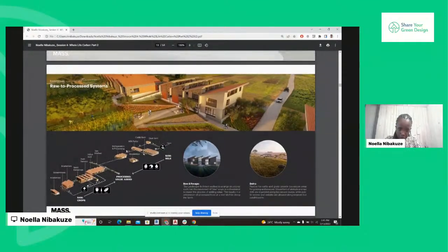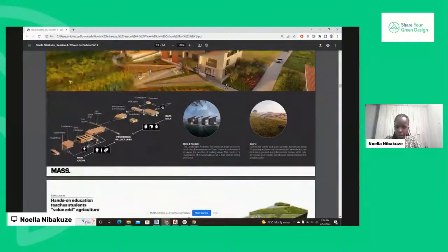Again, a section facing north. Some of the longer faces of this one face east and south. So we try to clad with terracotta bricks, and also recess it so that we avoid the sun. That's why we have these big recesses on the east and western sides, and also clerestory facing north to bring in light and ventilation.